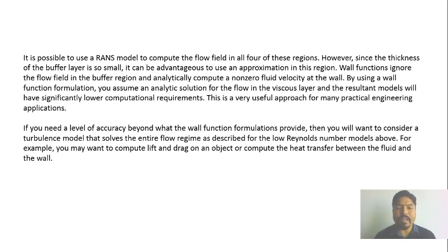By using a wall function formulation, you assume an analytic solution for the flow in the viscous layer, and the resulting models will have significantly lower computational requirements. This is a very useful approach for many practical engineering applications.